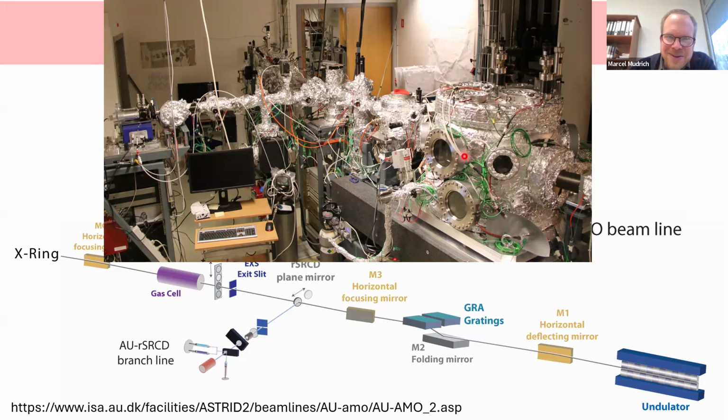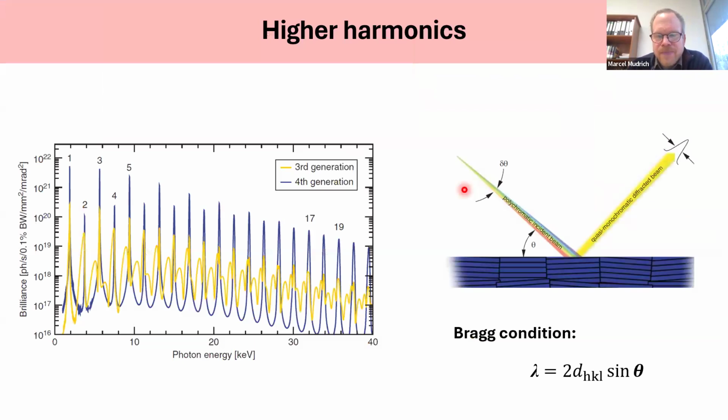And then once the setup is cooled down again, the vacuum becomes very good, because all the contamination is gone. So baking is the method of choice if you want to reach ultra high vacuum. And that needs to be done for the whole setup, including this big tank that houses folding mirror, gratings, water cooling, and complicated mechanics. So this is quite a sophisticated device.